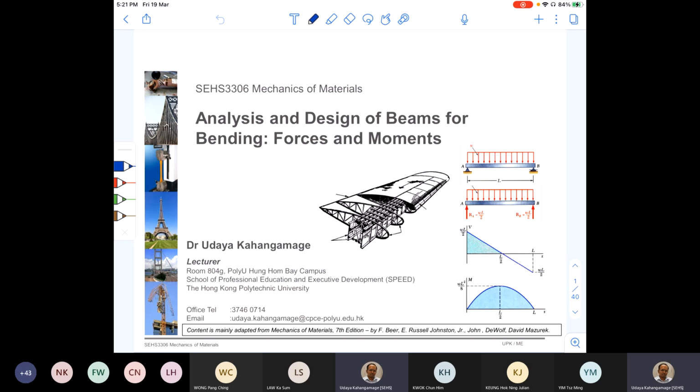We call it a bending moment because it creates a bending, and it is created by applying moment couples from the two ends of the beam. But most of the time, the beams you find have loads applied in the transverse direction, that is not along the major axis, but perpendicular to that, like shown in this diagram.